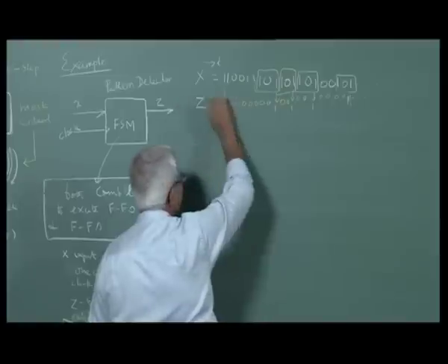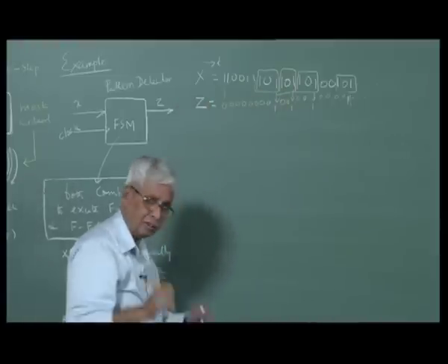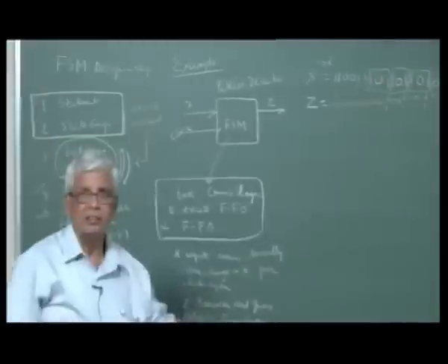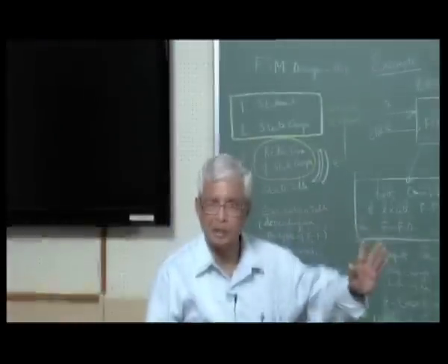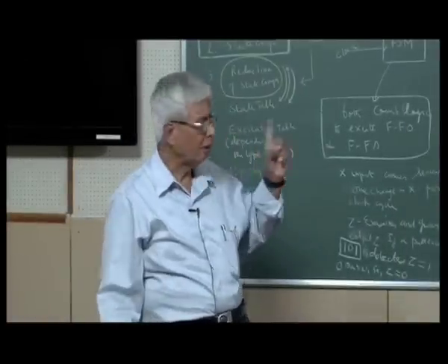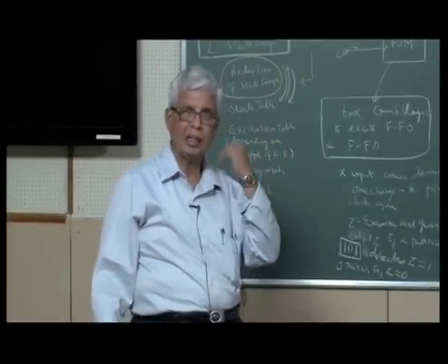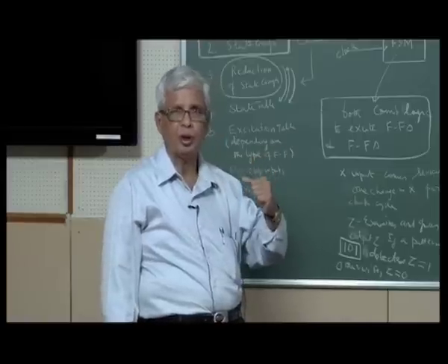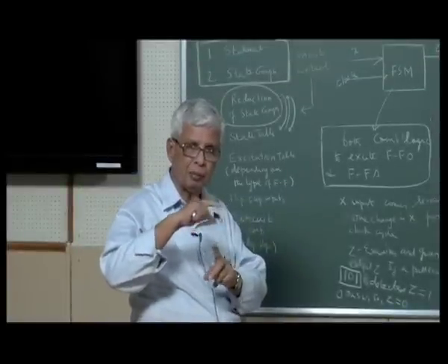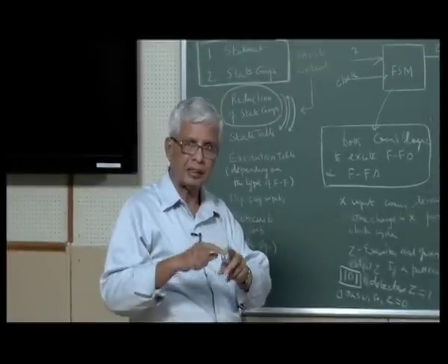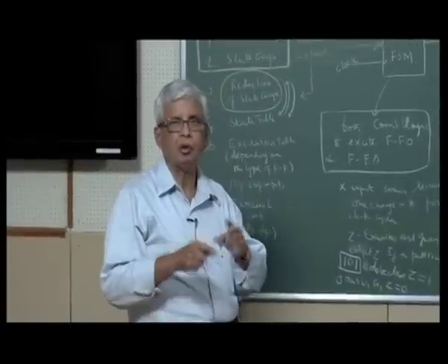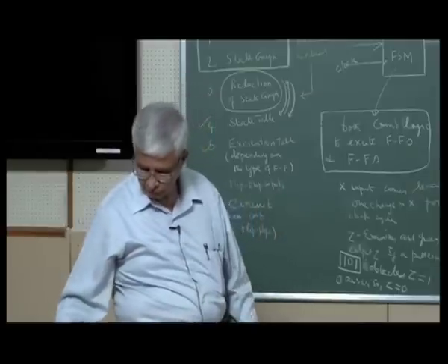So given this test pattern, given this input sequence, which is not fixed, once you design the circuit it should work for any input sequence, but the only thing it should do is whenever 101 is found in the input, the output should be 1 corresponding to this third bit. Rest of the time the output should be 0. That is a simple problem.